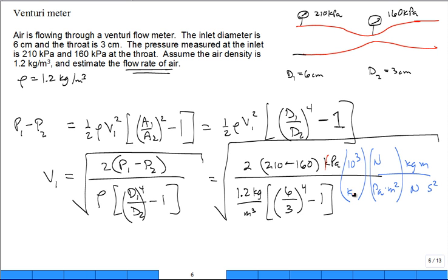The kilopascal, newton, kilogram. I get a meter with this. That'll kick up a meter over here, so I'll get meter squared over second squared, take the square root, I got meters per second. But don't forget the 1,000. Don't forget the 1,000 on the unit conversion, okay?